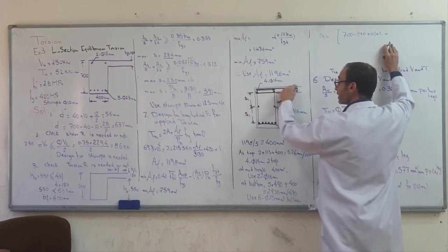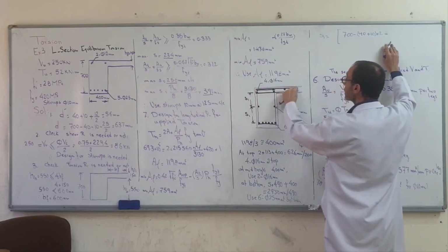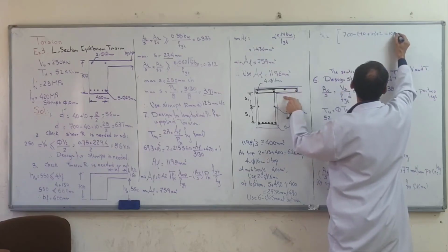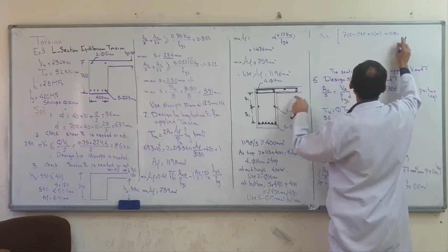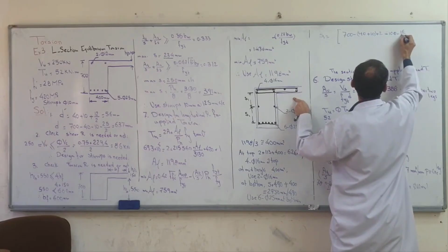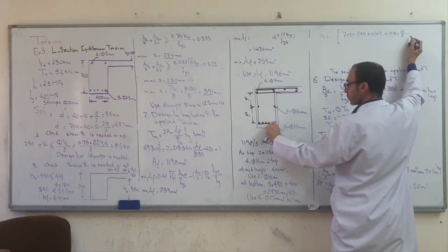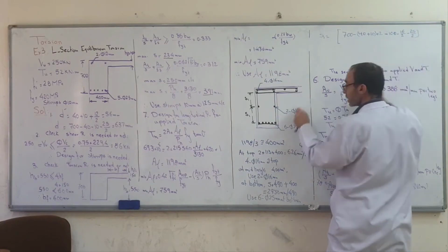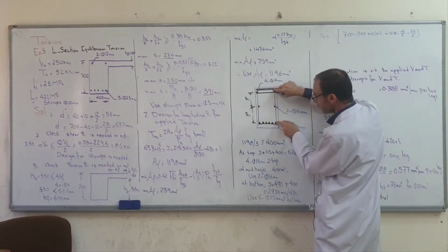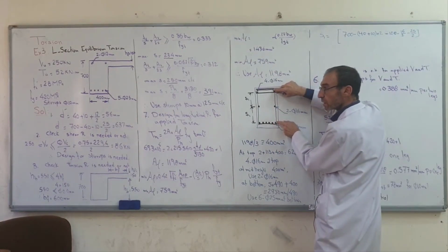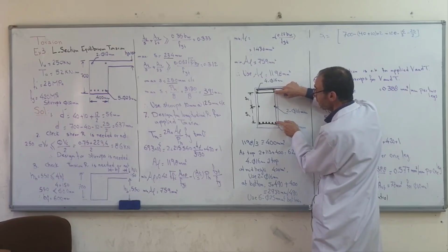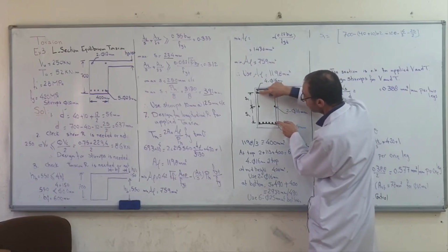100. We found 100. This is minus the spacing between these stirrups, 100 minus 5 over 2, 16 over 2, minus 25 over 2. We get the spacing between this bar and this bar, and between each pair of bars.